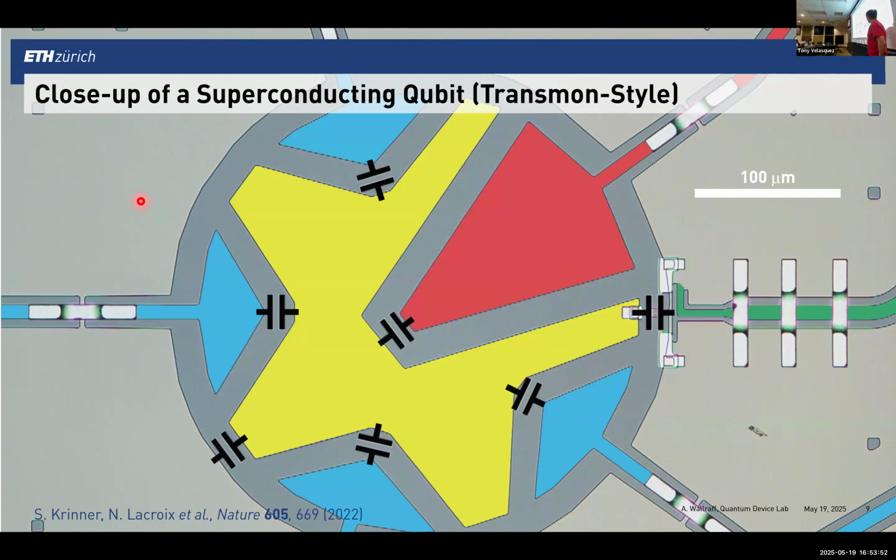In these transmon qubits, the parameters they have in the end rely a fair bit on displacement current. If the transmon qubit changes state, the charge distribution on this capacitor will change, and there will be image charges in the ground plane around it. When the qubit changes state, these image charges redistribute, and there need to be currents that flow.